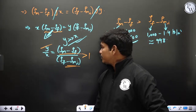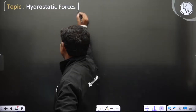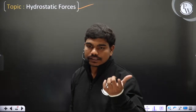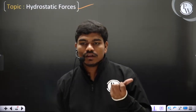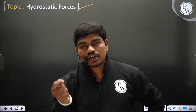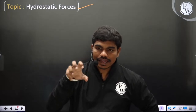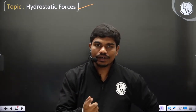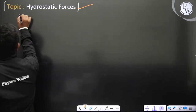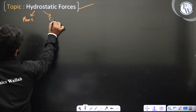Got it? Fine. Then we'll look at the next part, which is the hydrostatic forces. Till now the job was to calculate the pressure acting at a particular point. Now the next job is to know how much force this fluid will exert on any surface if you keep it in the fluid. Practically, we split this topic into two parts, plane and curved surfaces.